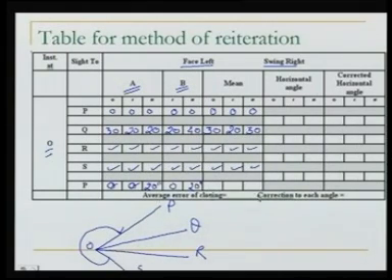So there is some error of 20 seconds, the error of misclosure. So this will be distributed. Now what we can do, using these values we can determine the value of the horizontal angle. I can write the horizontal angle: the reading to Q minus reading to P will give me the angle here, which will be 30, 20 and 30. Similarly, we can get these values of the angles also. So all these angles are written here.